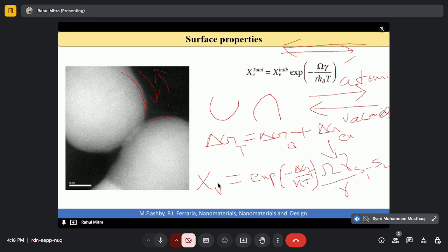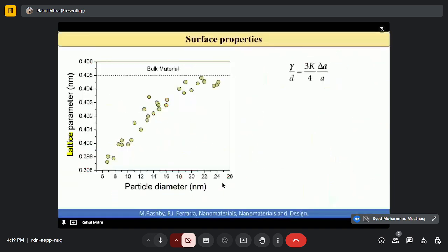Even once we prepare the nanoparticles and keep them at a nominal temperature, the atoms start diffusing to minimize the surface energy. The atoms diffuse from the concave surfaces to convex surfaces, and eventually we have bonding. So we need to study the properties so that these nanoparticles don't agglomerate or bond, like the sintering of powder particles. Now let's move on to this other topic.